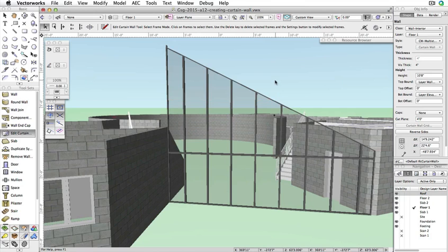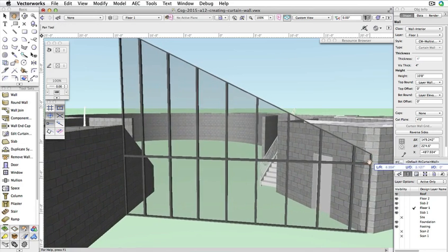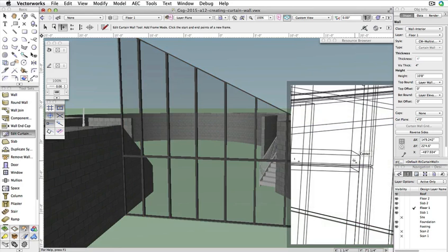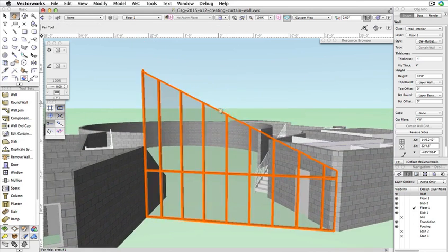Now, activate the Add Frame mode in the toolbar. Click the bottom right corner of the rightmost panel on the top row. Press the Z key and activate the Snap Loop if necessary. Then, move your cursor along the top angled frame and press the T key to acquire the Smart Edge. You should notice a red extension line following the same angle as the frame.